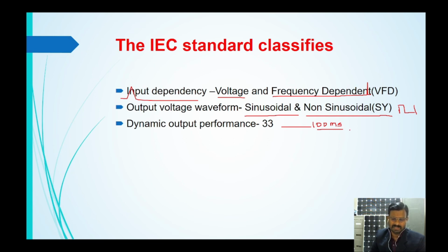Almost 10 millisecond interruption will be there in both modes. Whether you apply or remove the load, it has the same surges. And when you change the mode between stored energy mode and normal mode, it also takes time, with a 10 millisecond interruption.